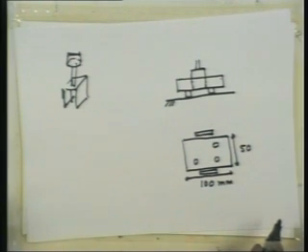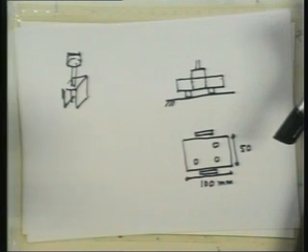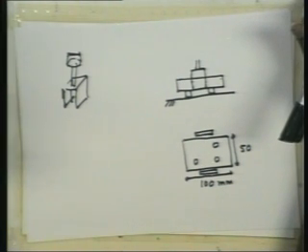Okay. Now in order to specify the end effector position and orientation, after the object is gripped, we need to know the relationship between the object and the gripper, because what we know are the initial and final location of the object and not the end effector. So after the gripping is done, we need to know the relationship between the object and the end effector, in order to be able to say where the end effector should be when the object is at these two positions, right? So that is why we need to decide on how to grip.